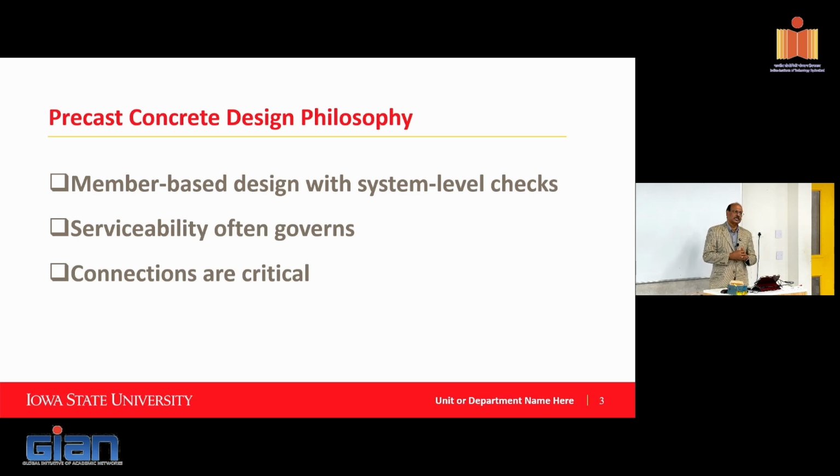So the designs are done at the member level because the loads have to be figured out at the member level, because precast components are basically, each of the members are what they're going to be producing. But at the end of the day, the necessary check has to be done at the structure level, right? The structure is the one that has to take the load. Once a design is completed and constructed, then it becomes a structural problem. So when I say structure, that includes the connections and their performance as well.